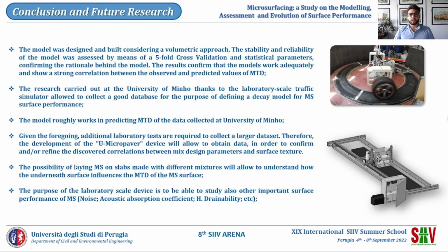So, to conclude, the model works adequately in predicting the MTD. The first experimental values for the validation are quite representative, apart from the influence of the underneath surface. The research at the University of Minho allowed us to collect data with the purpose of defining a possible decay model for microsurfacing surface performance. Given some limitations of the model, additional laboratory tests are required, and therefore the implementation of the prototype will allow us to collect a larger set of data.